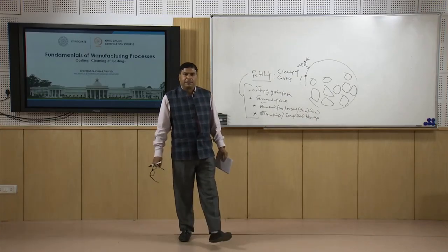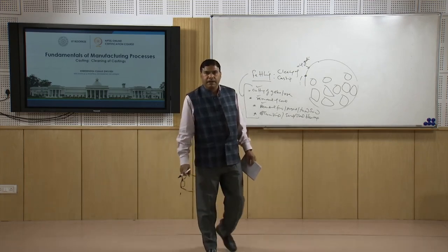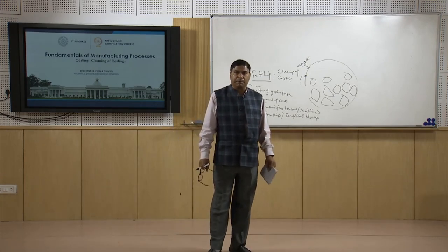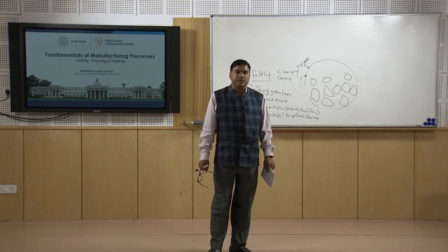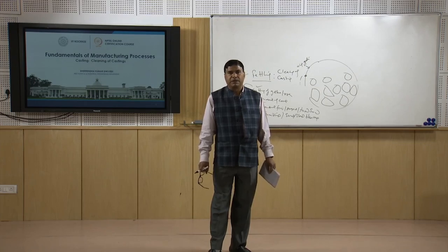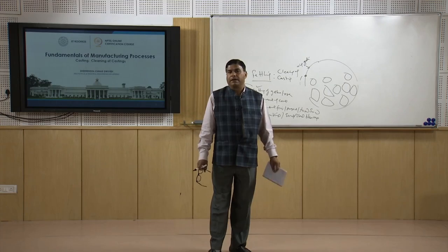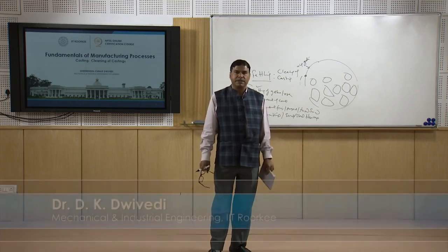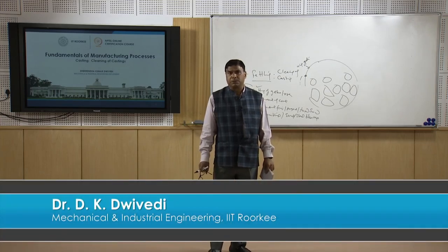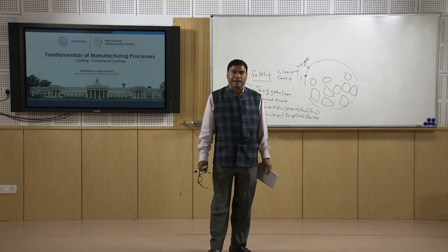So, now I will summarize the presentation. In this presentation I have talked about the temperature at which the casting should be extracted from the sand mold by breaking the mold, and once the mold is broken, then we need to remove a number of undesirable features which are present in the casting, for example removal of the gates and risers and removal of the fins, projections and undesirable materials which are deposited on the casting surface, so that a clean and usable casting can be produced.